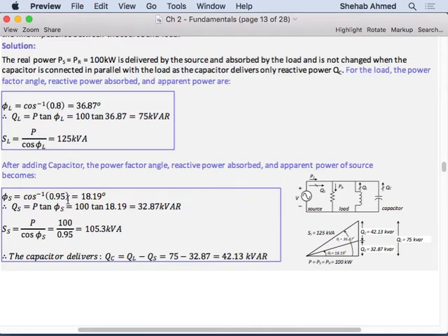The new ones, maybe there are better regulations now, but yes, very poor. Fluorescent lighting, unless it's the very expensive kind, because it's power electronics based, but not necessarily power factor corrected. With power electronics, you can do anything to the voltage and current, right? So fluorescent lighting has a poor power factor.